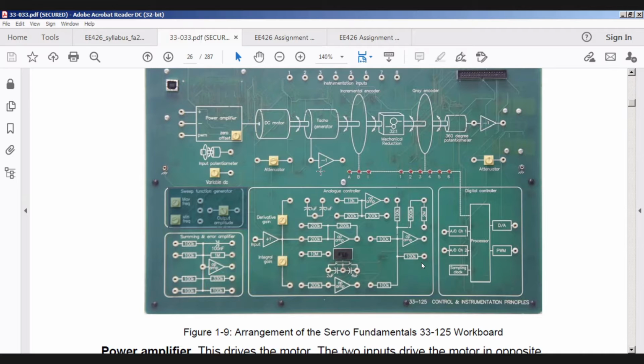So this is why we are interested in using MATLAB as a tool, so that we can actually generate the responses, so that we can understand how this motor fits into the general schematic of a closed loop control system. All right, so this is why we need step responses, we need square wave responses, sine wave responses, right?